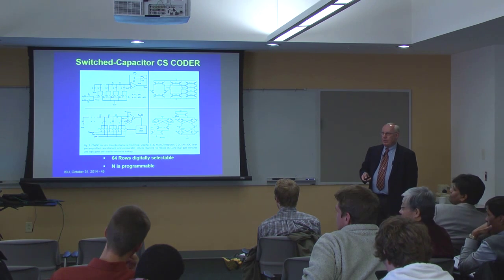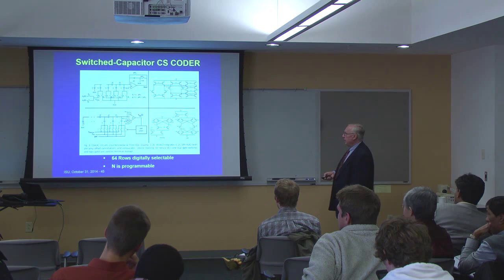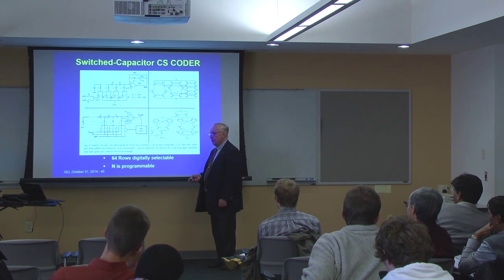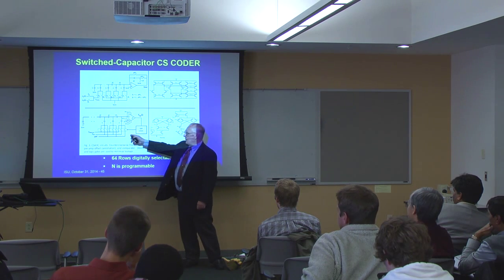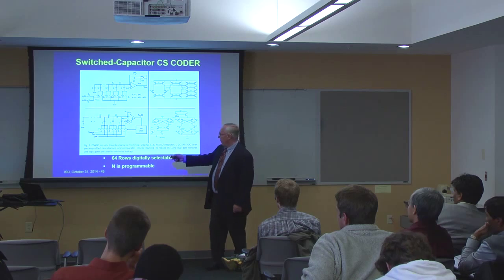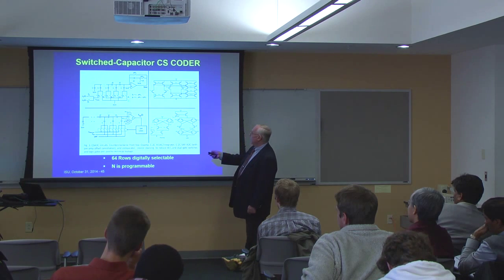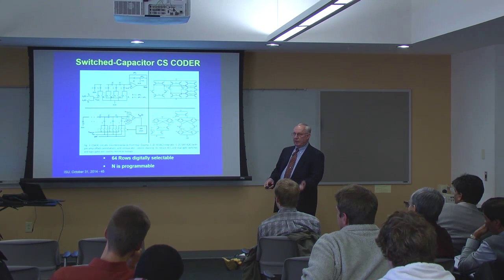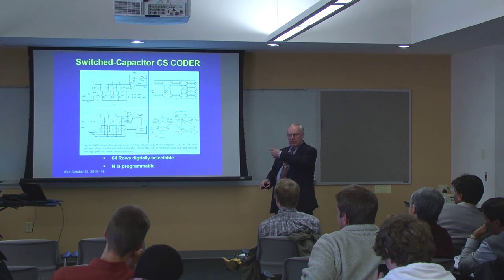The same reason? Slightly different. If you have to charge the capacitor array up to the value of the input signal, what's the total capacitance that you see in one of these structures, looking in from the bottom? It's like C or 2C.